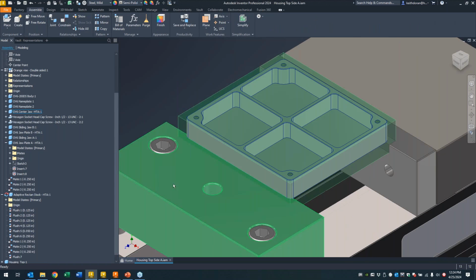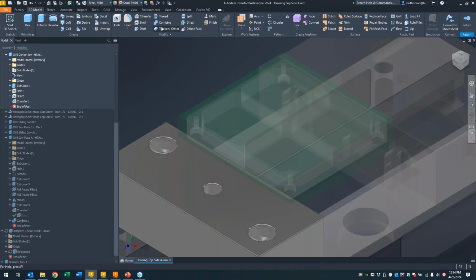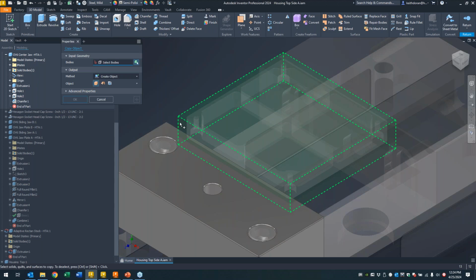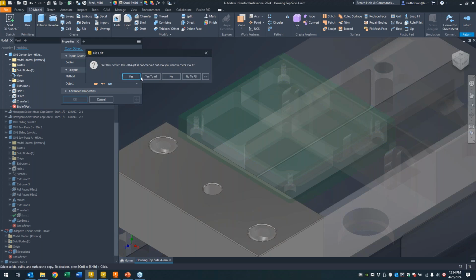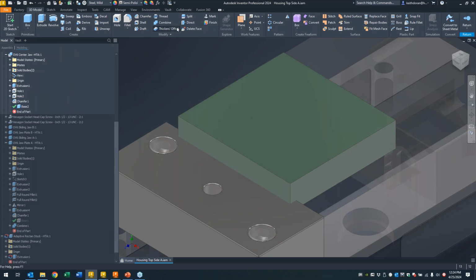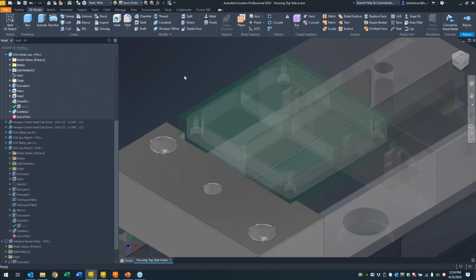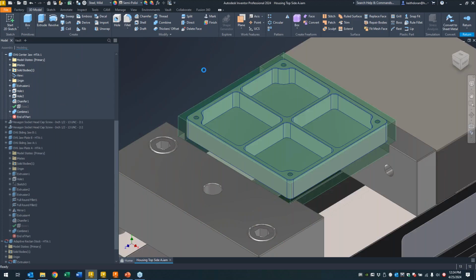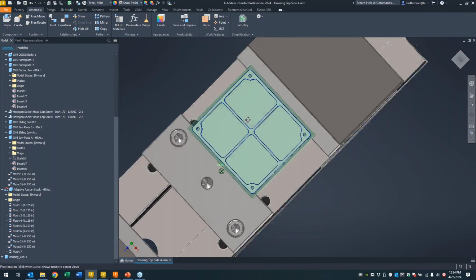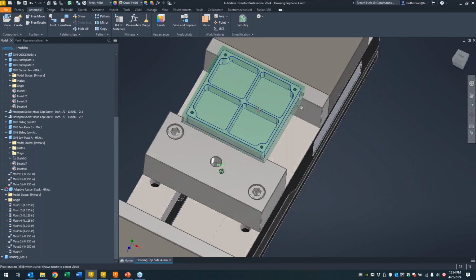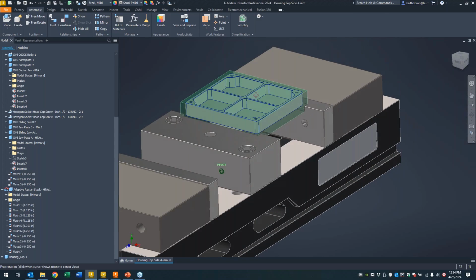From here, I can finish that edit. I'll repeat it on this file. The one big trick to this, make sure you tell it to use the solid option. If you leave this as surface, the combine tool won't work because it's not watertight. It's not a solid, right? And there we go. So finish the edit. And then again, we can see there, we've got our definition built up as far as those fixtures are concerned.